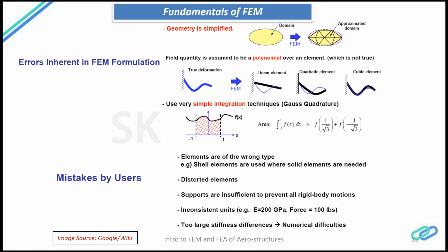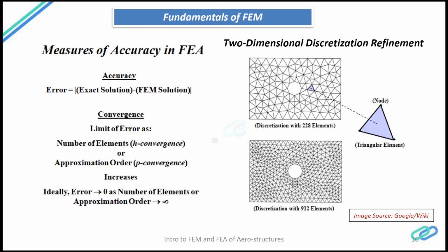While creating the material properties, finite element engineers might commit errors, so there might be an inconsistency in units. And then finally, large stiffness differences. This might be the result of not having the proper assumptions, not knowing how to idealize the real structure into the mathematical model. This falls into the idealization error. Later on we will discuss these things in much more detail. So moving forward,